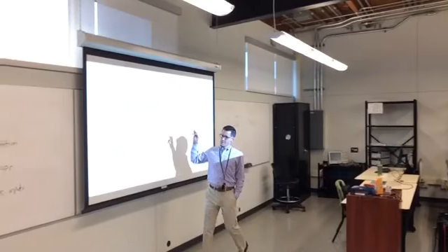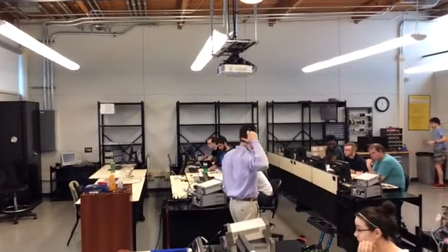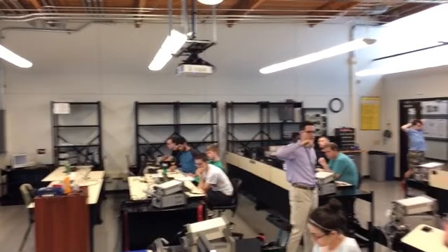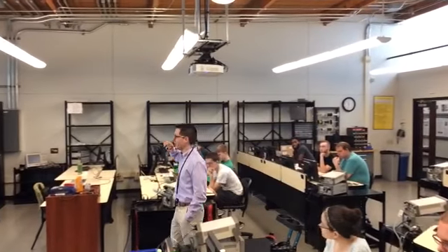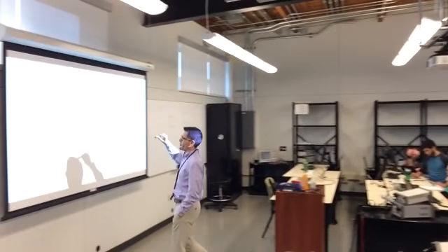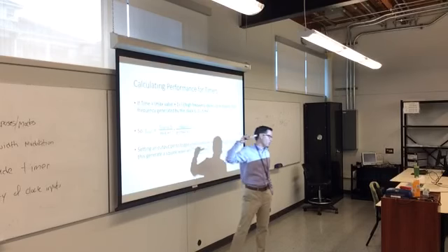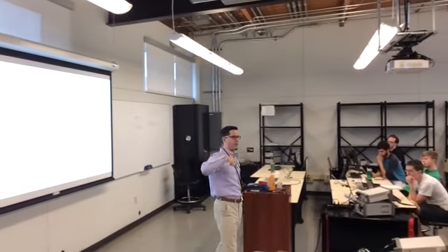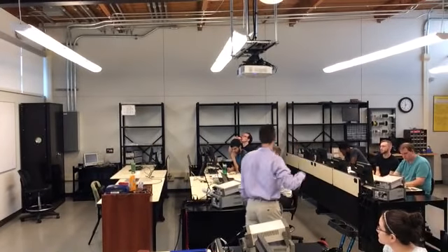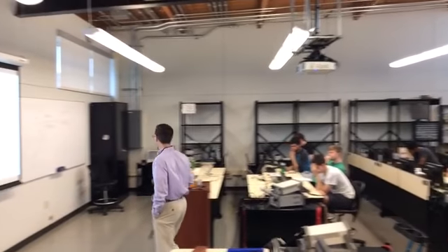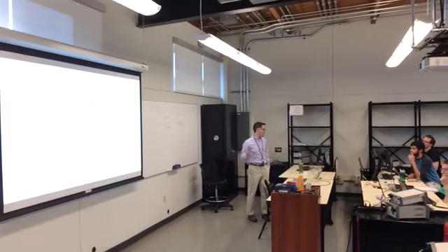Now, here's an important point if you're going to try to generate a wave. That calculation right there takes our time period of counting through an entire timer. If my timer just counts up, this is the maximum frequency it'll count at. And so you might say to yourself, well, I want to generate a square wave, and every time that timer pops, I'm just going to toggle a pin. And that'll guarantee to give me a square wave with that frequency right there. And it's not going to do it. You're going to be off by a factor of 2.